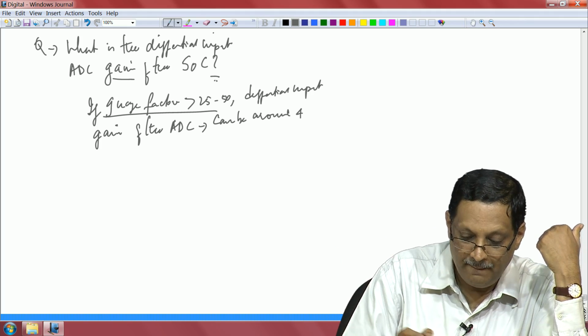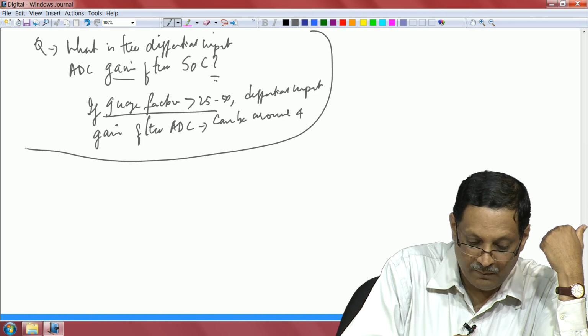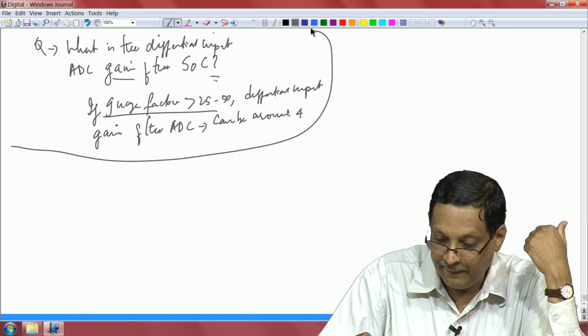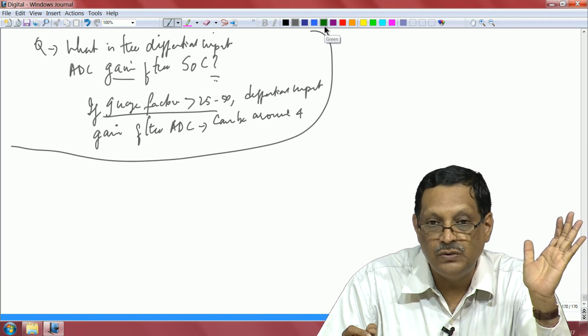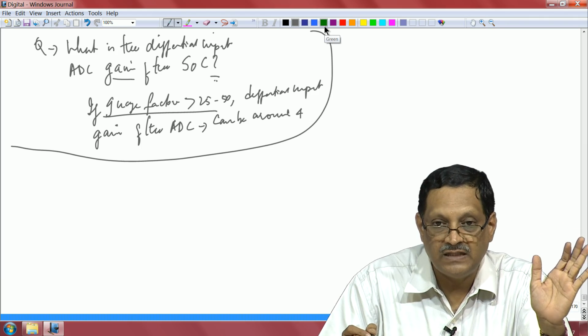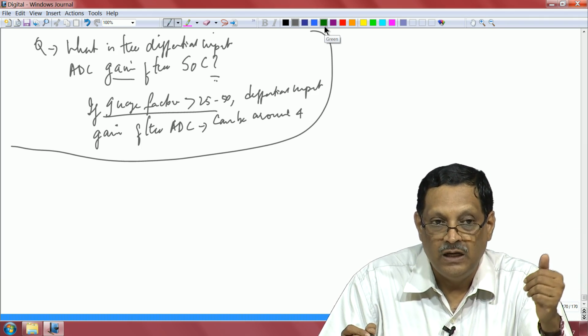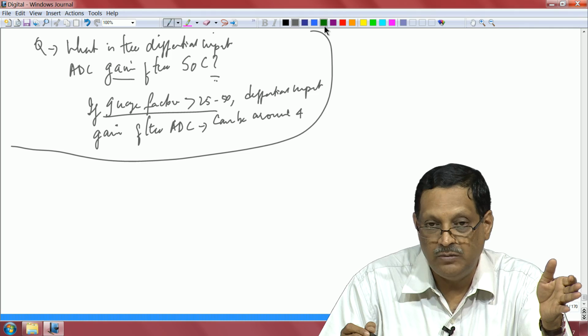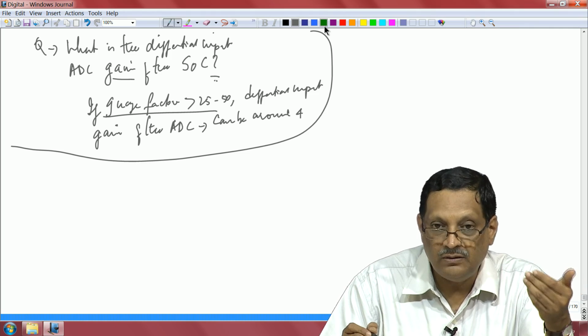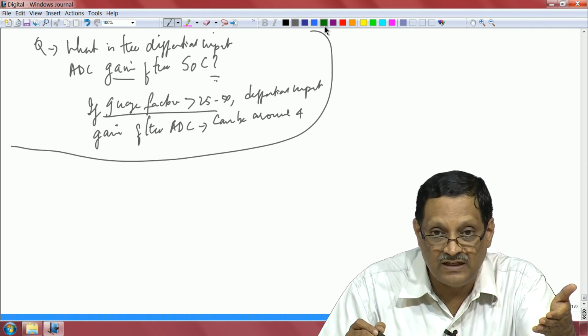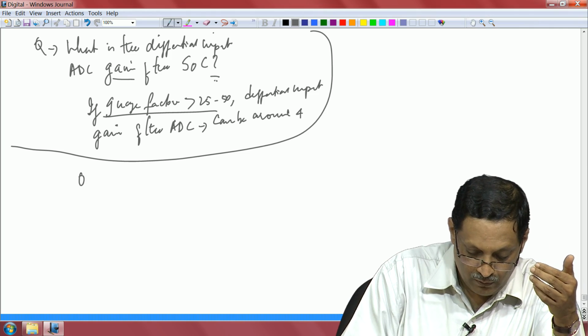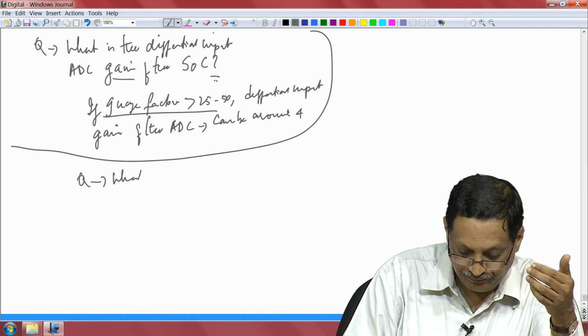So, you see now this is the big summary, and you just can't choose a controller because it has an 8-bit ADC or a 12-bit ADC or a 16-bit ADC and so on, but you also have to keep in mind what are the sensors that you are going to connect.